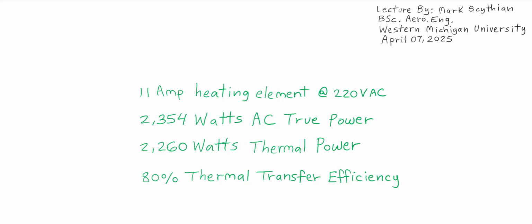So this is just a lab example video about how you can measure the heat transfer through water and then calculate the source thermal power. And then in this case, it's from electricity. So you can go the other direction and figure out the electrical efficiency and then actually calculate the source input power. And then because it's a heating element, the power factor is 1, you can just divide that input AC electrical power into the voltage and then get the amp rating per, at least in this case, the large heating element. So this is just an exercise in the conservation of energy.